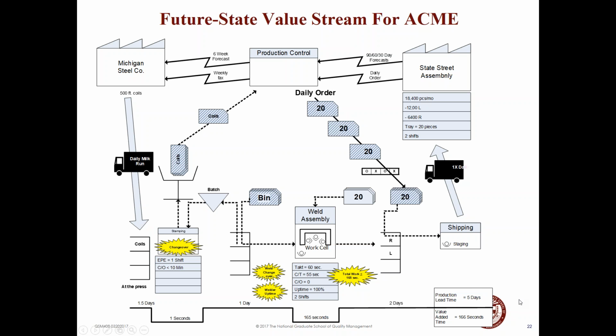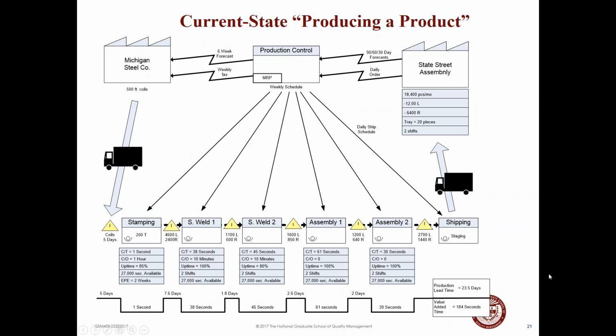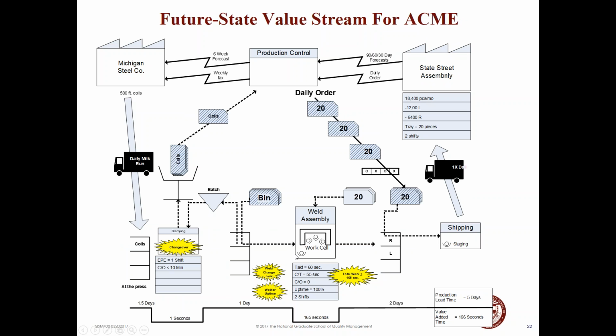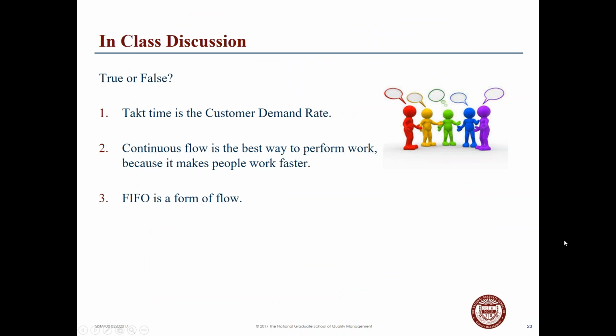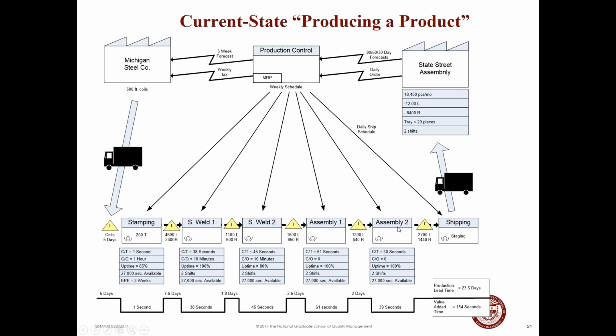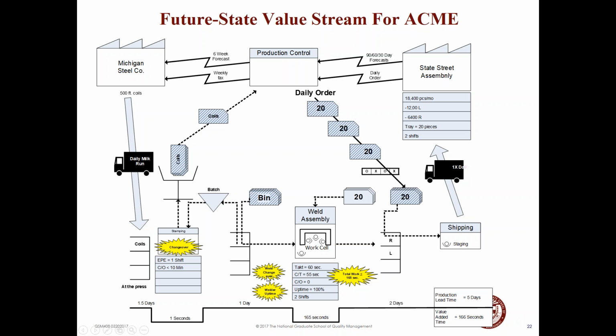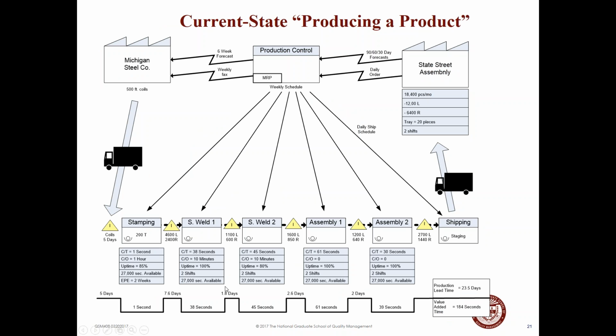So if I do a little flashback, you've got stamping and 2 welders. And over here, we've got stamping and we have 1 welding. And what they've done is they've merged the welding and the assembly together into a work cell. Before we had stamping, 2 weldings and 2 assembly for 5 stations. You now have a stamping station, and then it's being moved over into a welding station, which is doing all the welding and assembly at one place. And so they've used a workstation to allow them to increase and improve the takt time. So all these elements of each and every phase have been dramatically improved.